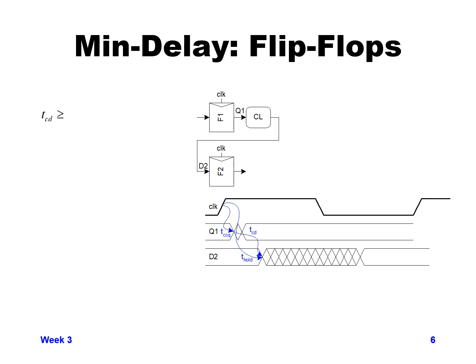it was supposed to. So the equation for that is your T sub CD, or combinational delay, has to be greater than your hold time of your receiving flop minus the contamination delay clock to Q of going through the phase F1 flop.